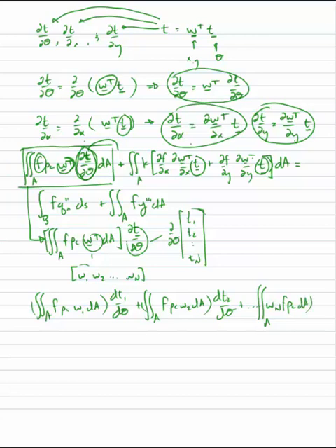So yeah, if we just go through all these terms in that way, this ends up looking like a really big equation. So the integral over the area of F times rho c W1 dA times dT1/dθ, plus all of these up to the integral over the area F rho c Wn dA and dTn/dθ. So that's basically this part of the thing written out, and then we can do the same thing here.